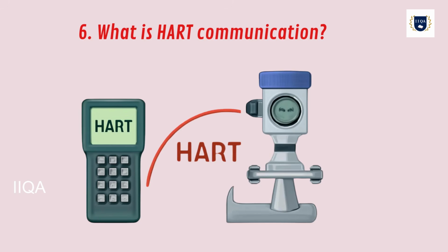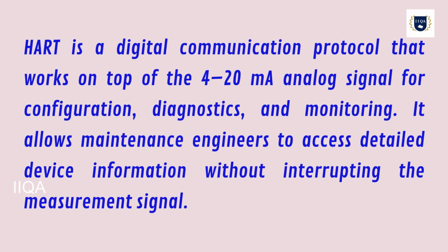What is HART communication? HART is a digital communication protocol that works on top of the 4 to 20 mA analog signal for configuration, diagnostics, and monitoring. It allows maintenance engineers to access detailed device information without interrupting the measurement signal.